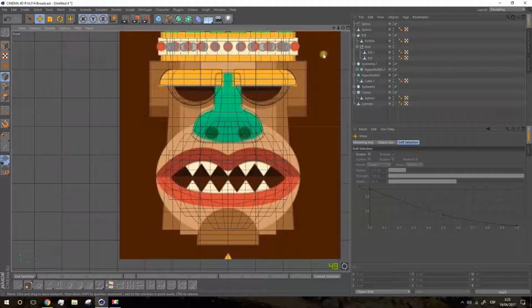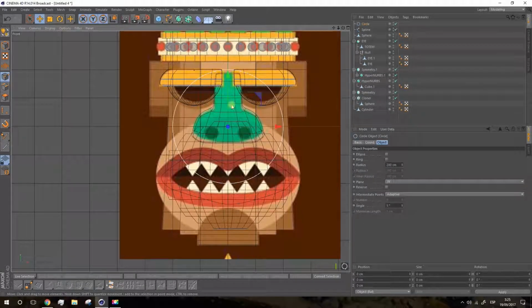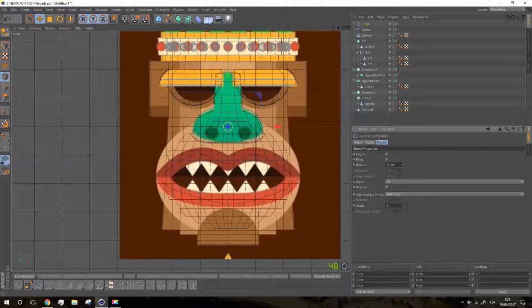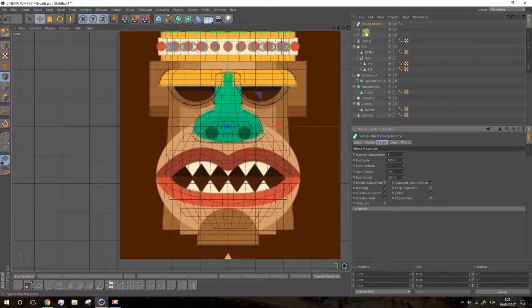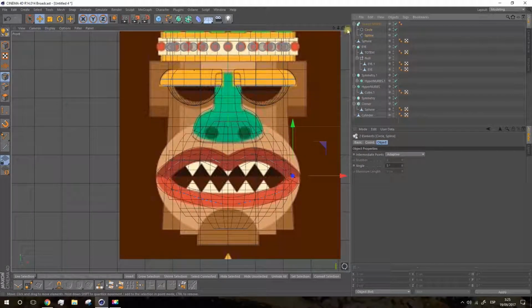So once we have this done, you'll notice that the spline by itself doesn't do anything. So we need to use another type of ready-made spline, which is a circle. We'll first make this circle smaller. So here in radius, we'll decrease the size quite a lot. So 24, for example. And now we'll apply another property, which is this one here, sweep Nurbs. Take the circle and the spline and place them inside this.